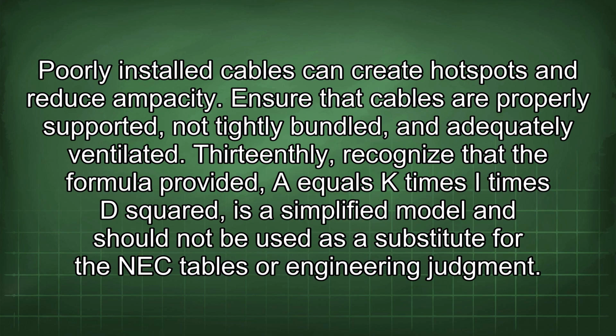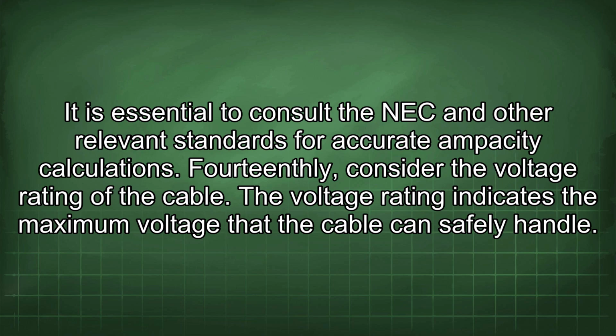13thly, recognize that the formula provided, A equals K times I times D squared, is a simplified model and should not be used as a substitute for the NEC tables or engineering judgment. It is essential to consult the NEC and other relevant standards for accurate ampacity calculations.